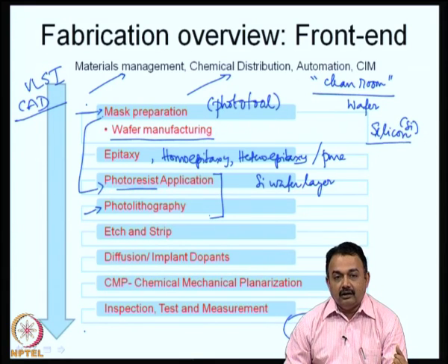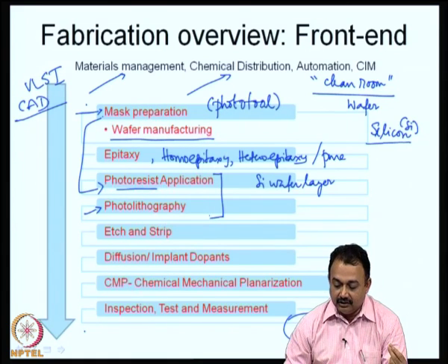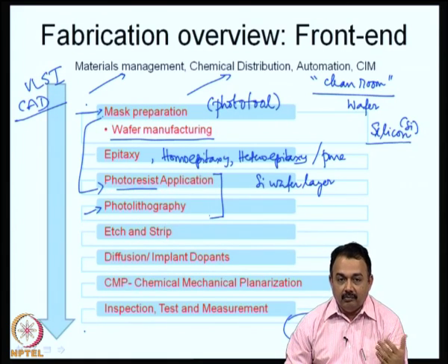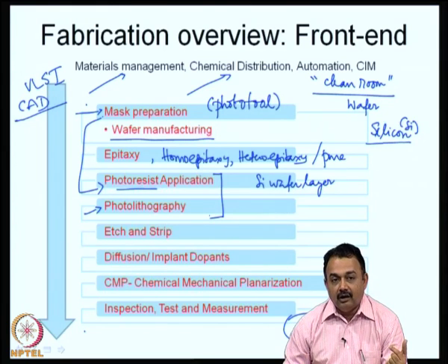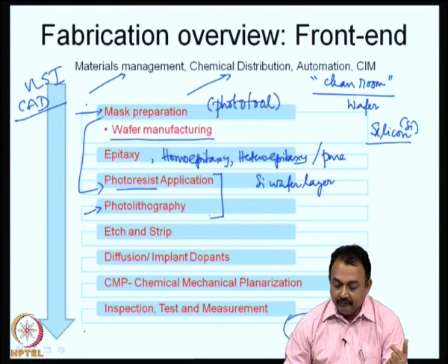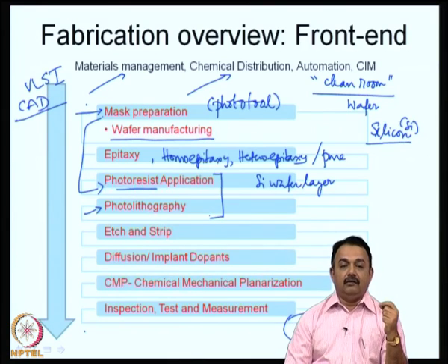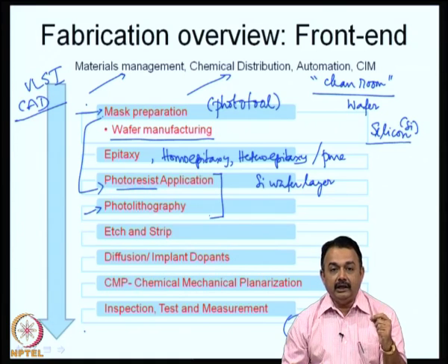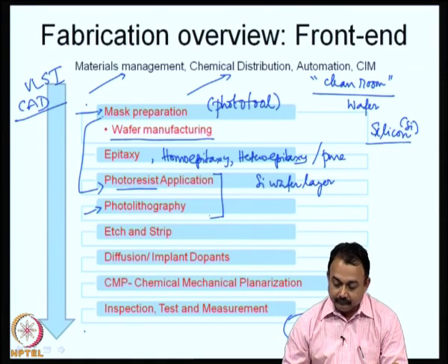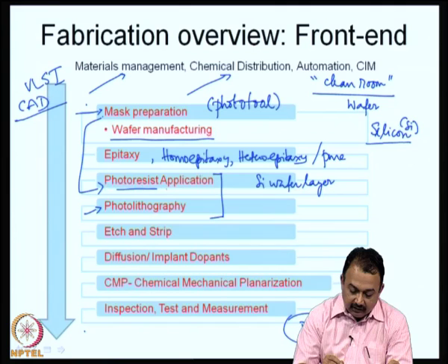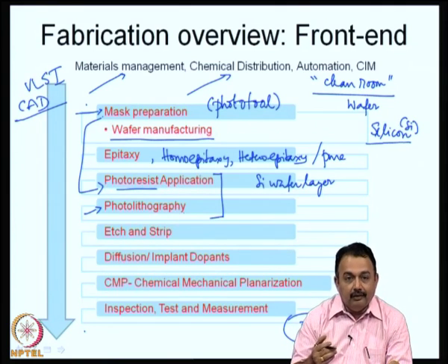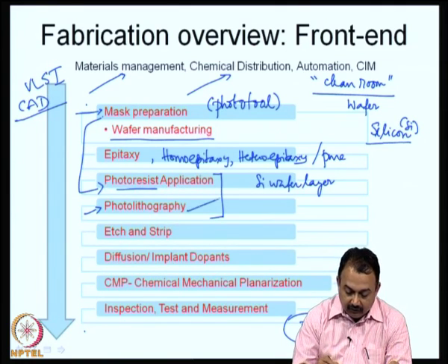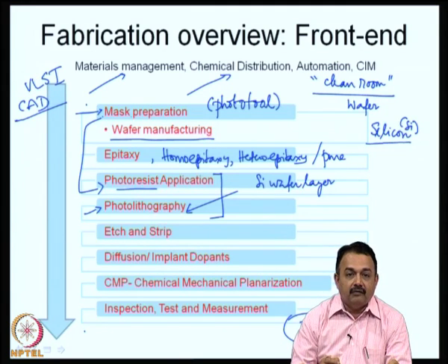So, typically currently the industry uses a wet process for photoresist application, and there will be a dry imaging process that follows the wet process of application of a photoresist, and therefore, the resolution that is got from the photoresist is very important in defining the yield rate from every wafer. So, after the photoresist is applied and it is cured, then we use a photolithography using the mask that we have generated for a particular layer.